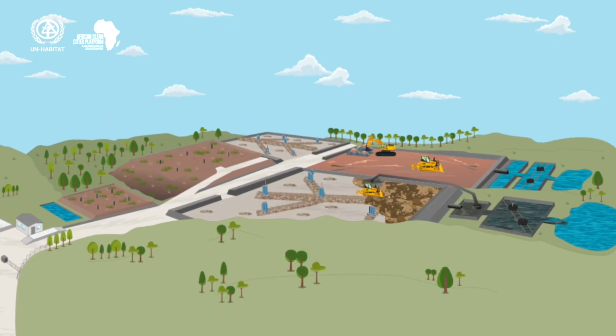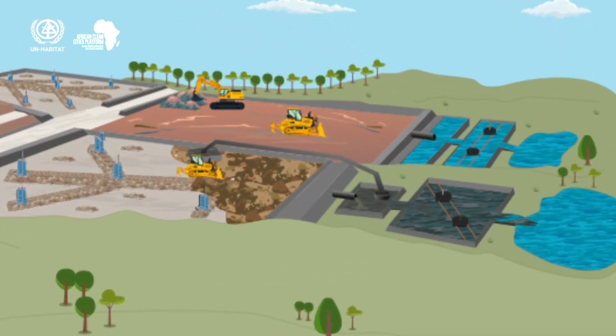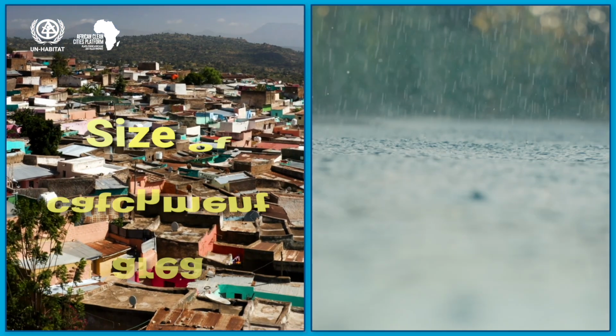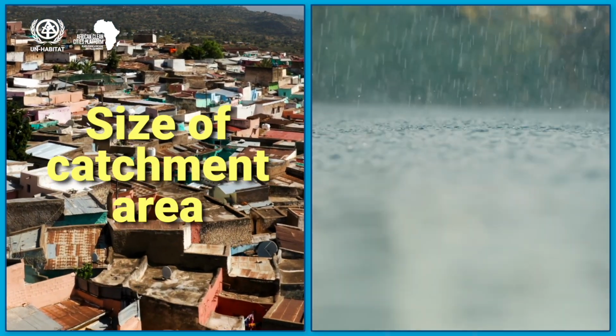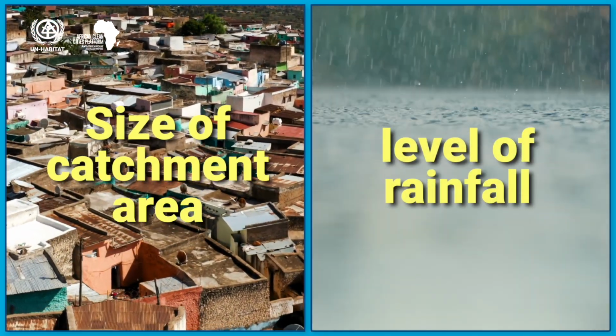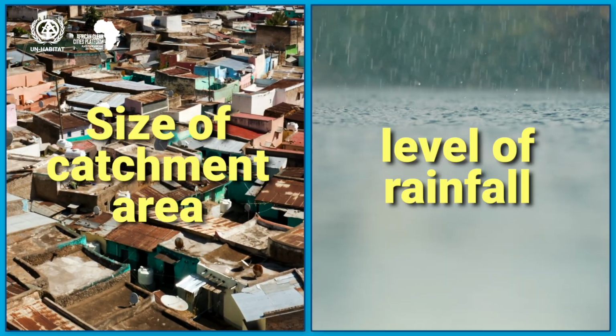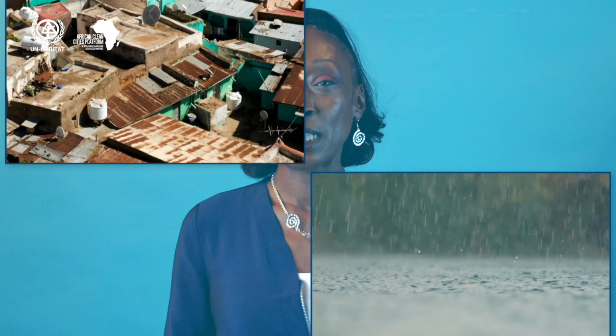This is a facility connected at the downstream end of the leachate collection pipes. The pond collects the leachate and further reduces its pollution level. The required capacity of the pond must be calculated by considering the size of the catchment area the landfill site serves and how much rain the region gets. There are various ways of treating leachate.